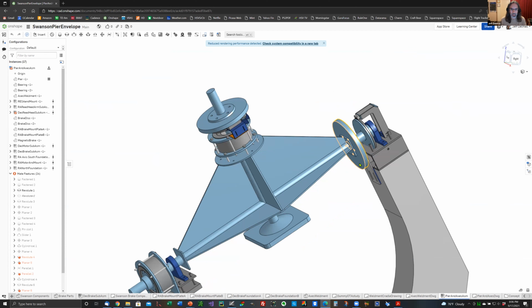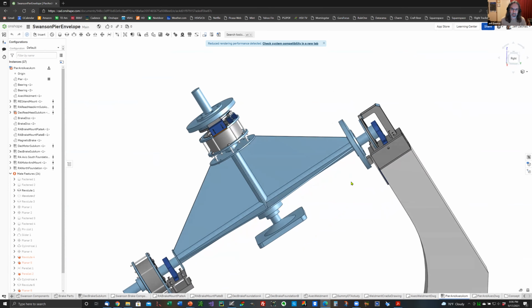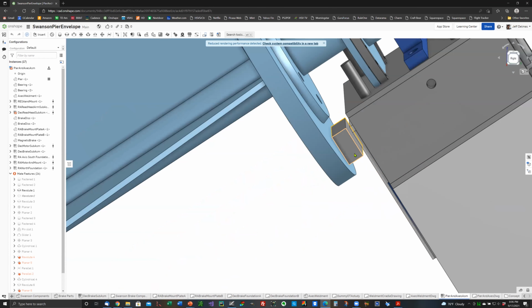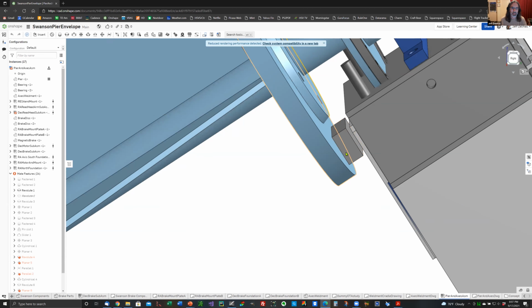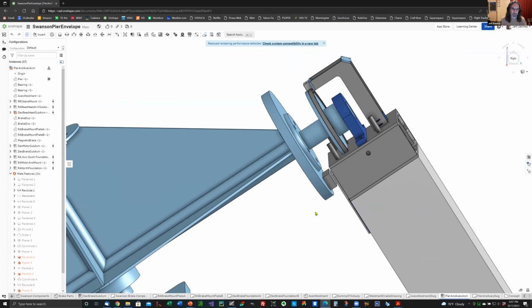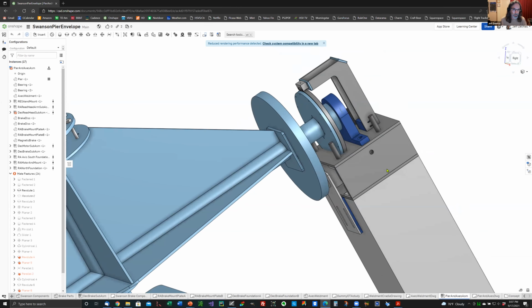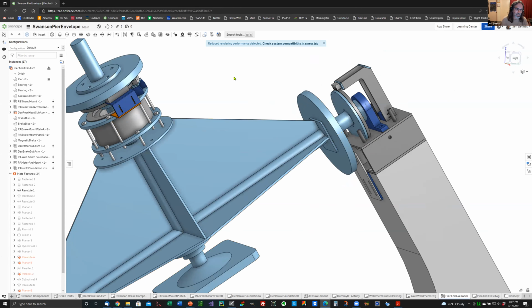What we're doing is we've got, this is actually just a standard car disc brake, and then we're mounting magnetic door locks. Often at corporate offices, you'll go up to the door, and if you have card key access, you can push on the door and it'll open for you. Otherwise, you push on it and it won't open. And that's a magnetic door lock. And that's what this little block here represents, is that magnetic door lock. We're using it in a very different way than it was designed, because we're using the friction of the magnet against the brake disc to induce torque, a force, to slow it down and hold it steady, basically.